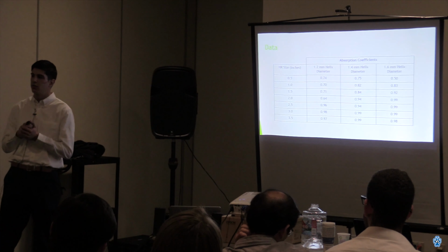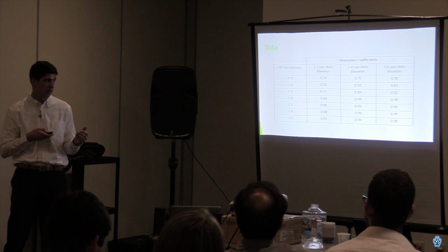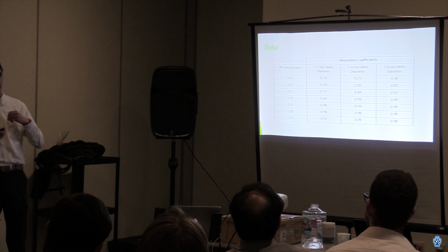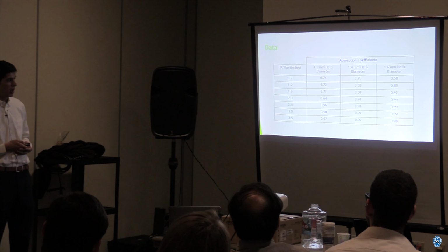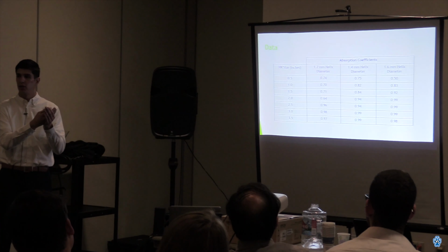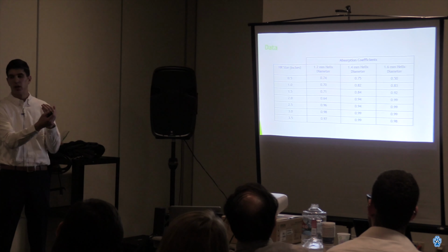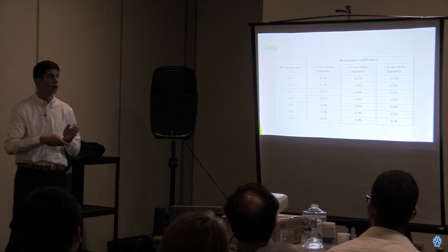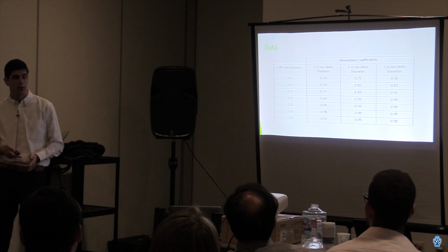Every time a sound wave interacts with a surface, some of it gets transmitted and some of it gets reflected. The reflected part is from the standing wave, and then part of it gets transmitted through the material itself. The reason why these are so high is because the part that's reflected from my material and the part that's reflected from the back cavity are in separate phase, so when they both reflect, they cancel each other out. So it looks like it got a lot of absorption, but it all just actually got transmitted through the actual thing.